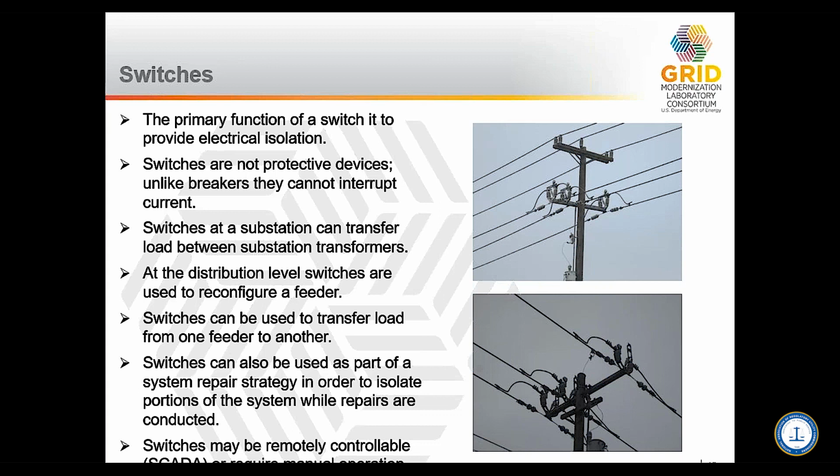And then switches can also be remotely controlled, just as breakers can, through your supervisory control and data acquisition, or SCADA, system, although they generally tend not to be operated under load because, as I said, they're not designed to interrupt fault current. They're just simple, kind of dumb knife switches like you'd see in a Frankenstein movie. And so operating those under load can cause damage to them. The advantage to them is they're cost effective. While a recloser will cost tens of thousands of dollars, and it can cost a lot to mount it on the system, these are far cheaper to purchase, with less maintenance as well.